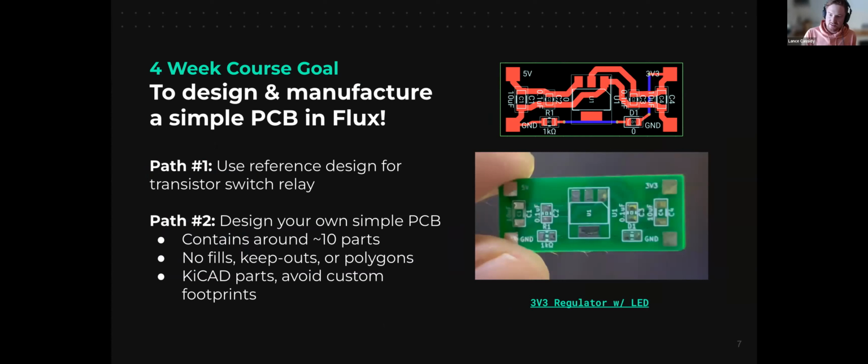Okay, what else here? The switch, the 151563. Let me search 151563. Okay, there you go. Created by the username Basil. It has a usage count of 20. It has a footprint and 3D model. Okay, I'm good with that. I'm just going to drag that one here on the canvas.